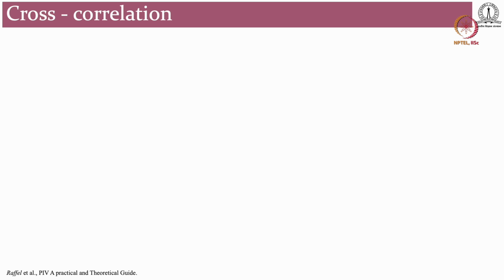So cutting a very large story short, PIV, as already told, we are not tracking a single particle, we are seeing how a bunch of particles passes through a window, and basically it's an Eulerian method, unlike PTV, which was normally a Lagrangian way of tracking particles. So here we are doing nothing but searching for a zone in a future frame, at delta t, that matches well with the current frame's interrogation window.